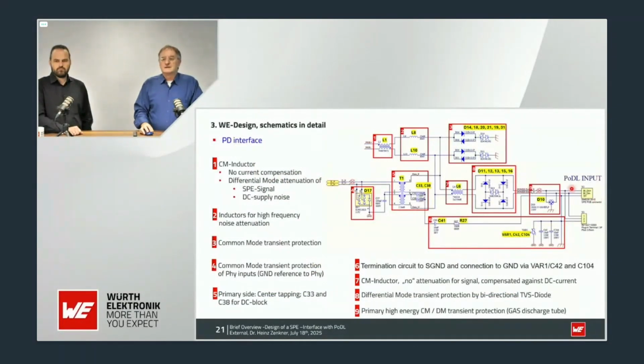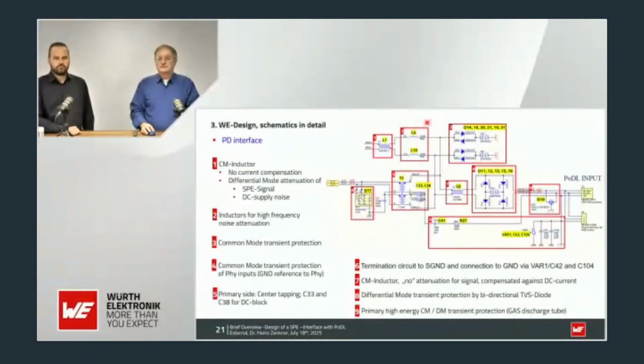What is important to know here, we have the two different grounds: the shield grounding for decoupling and absorbing the first amount of energy in terms of transient protection, and then the secondary side, where we have the ground system. Together, this gives you not only a decoupling of the transients by high impedances, it also gives you a decoupling of all this digital electronics in terms of radiated emission and conducted emission.